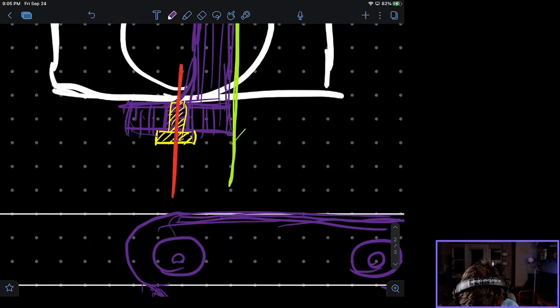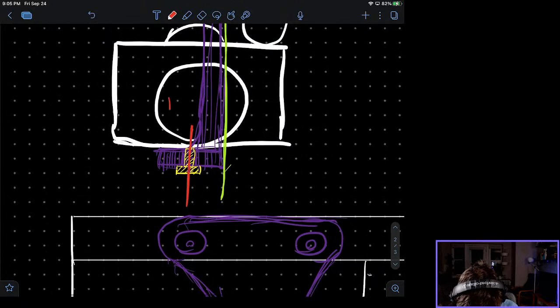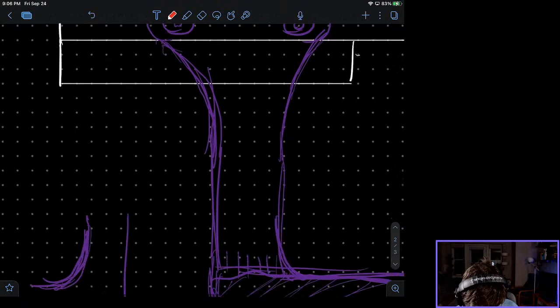Because these layer lines are vertical like that, what I'm worried is that the load of the camera will be right here, or part of the load, so part of the weight, and that will cause this to shear right there. So I got to think about this a little bit more. There isn't really a good position other than this bottom plate.